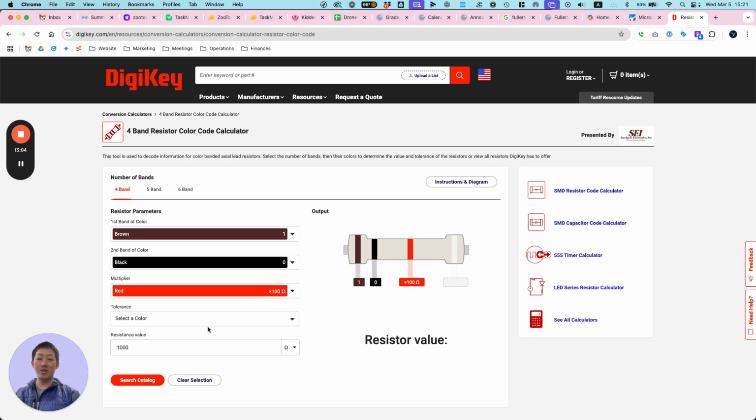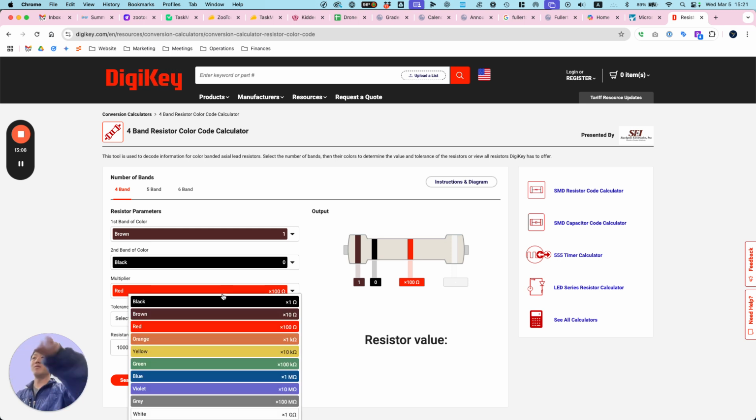If it's by 100, so now it's 1,000, which is kind of high, but we could probably just crank up the voltage more, okay? But if you have orange, yellow, green, blue, anything like that, this thing probably is not going to light up. So can you check your resistors on your board and make sure, ideally it's a brown in the middle as a third band.